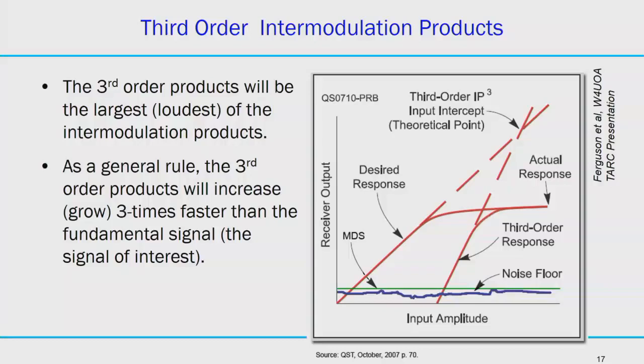So when you're designing circuits of different frequency bandwidth, there is no easy way of dealing with noise because it is bandwidth dependent. More bandwidth, you have more noise, right? So this noise floor is not any arbitrary noise floor that you see on the instrument. It needs to be normalized to 1 hertz of bandwidth. Only then do we have one unique way of telling how bad the noise is.